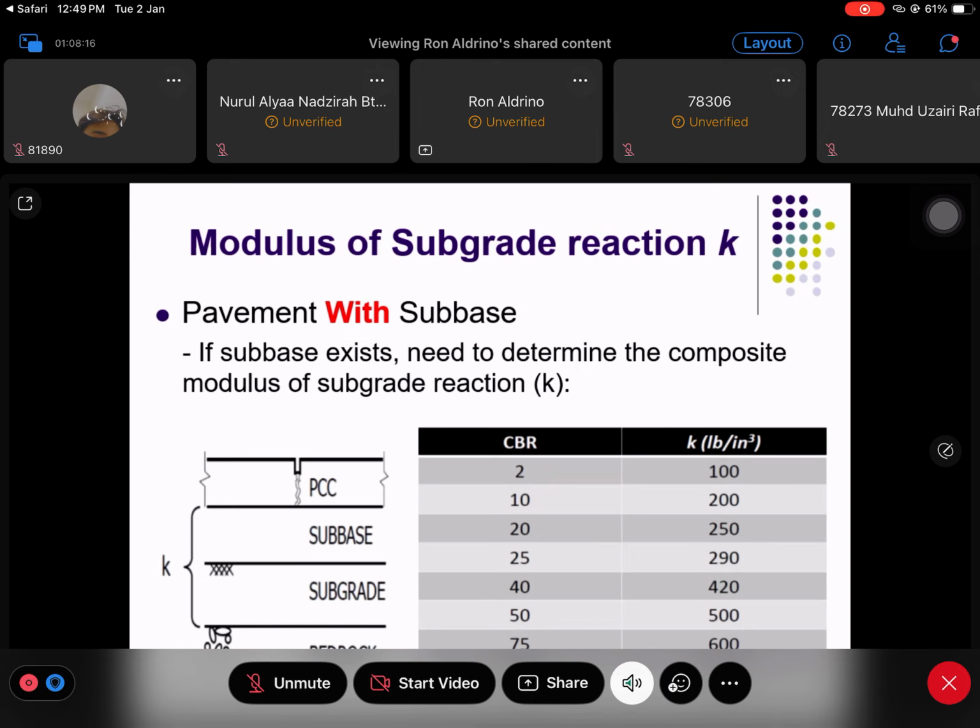So if you are designing with subbase, then you need to determine the composite modulus of subgrade reaction. And this is if you have an extra subbase, and you need to check the CBR value of your subbase as well. So if you have a CBR value of 10, then you need to input your K as 200 pound per inch cube. Okay.